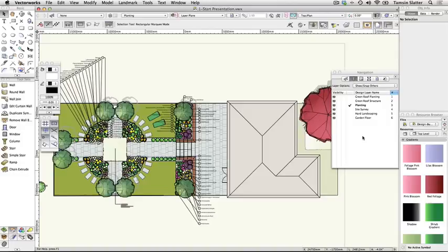Create sheet layers. Although we set the scale on the design layer and set the page size, I've mentioned several times that it really doesn't matter about page size on a design layer. Ultimately, on a sheet layer, you can present your model from any angle at any scale with as much information visible as you choose on a sheet layer. A sheet layer is much more representative of a physical piece of paper than a design layer.